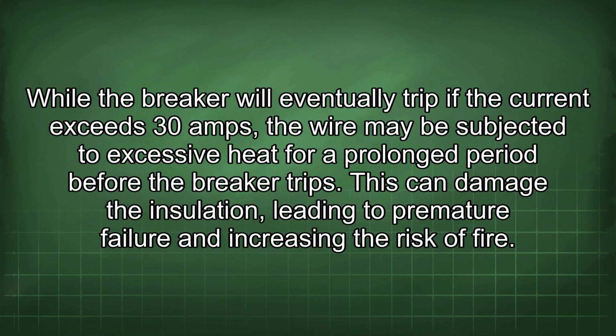While the breaker will eventually trip if the current exceeds 30 amps, the wire may be subjected to excessive heat for a prolonged period before the breaker trips. This can damage the insulation, leading to premature failure and increasing the risk of fire.